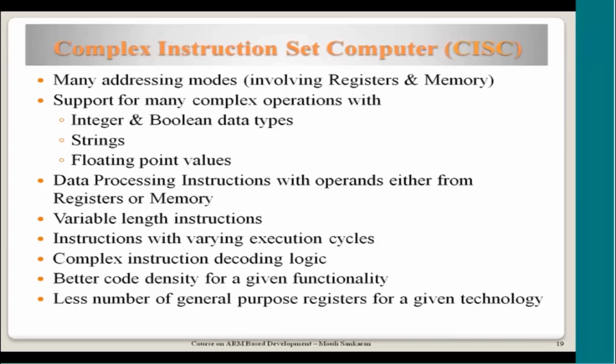Now, when you are comparing a CISC and a RISC processor, we need to keep the same technology in mind and then see whether the number of registers supported by these processors are the same or not. When we see that, we normally see that CISC processors support fewer general purpose registers because the space is consumed by other complex circuitry in the system. A very important part of that is the logic required for decoding the instruction. Examples are the earlier x86 family processors and Motorola 68K.